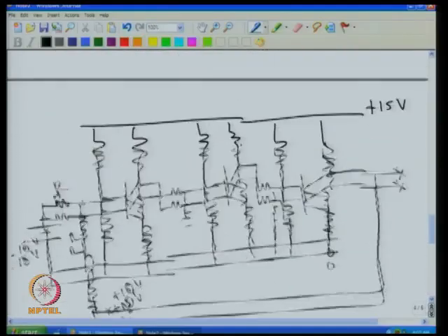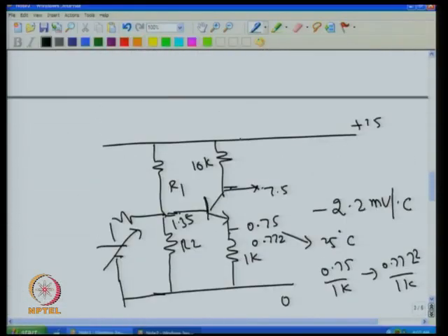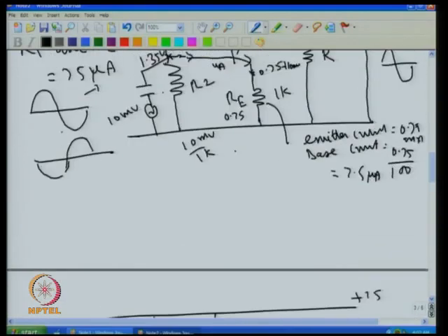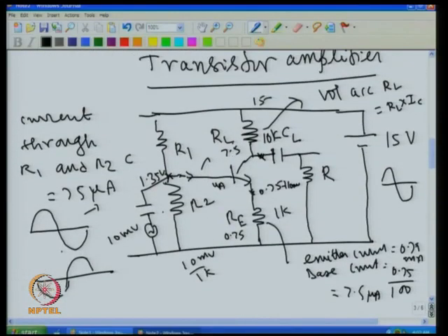So if you put this quickly, if you look at what we have done today, we started our discussion by explaining what a transistor amplifier is and how it works. Basically, whatever signal you give to the transistor is amplified with a 180-degree phase difference, and I showed you how to select this resistance and this resistance, because if I want a gain of 10, I have to make sure this ratio is 10. For example, this 10K and 1K give me a gain of 10. Then I should select these two resistances.